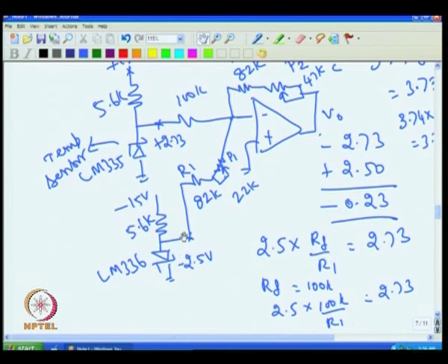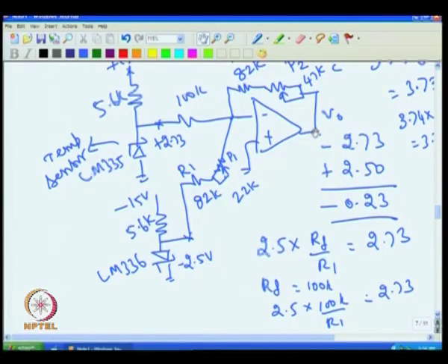We assume there is no other drift in this case. Even with this alone changing, it can have an uncertainty of 0.75 degree in this instrument. So, we have to see all other errors in the next session, because it is essential when we are designing an instrument to know what the total expected error is.